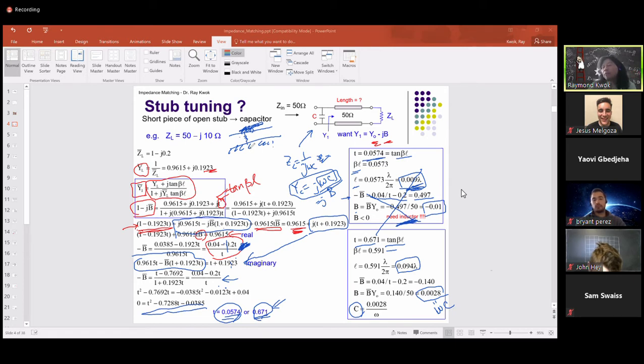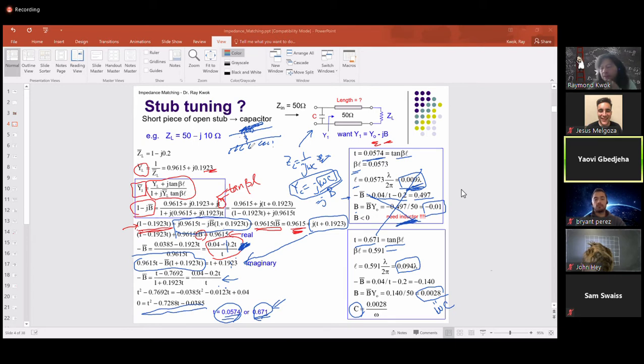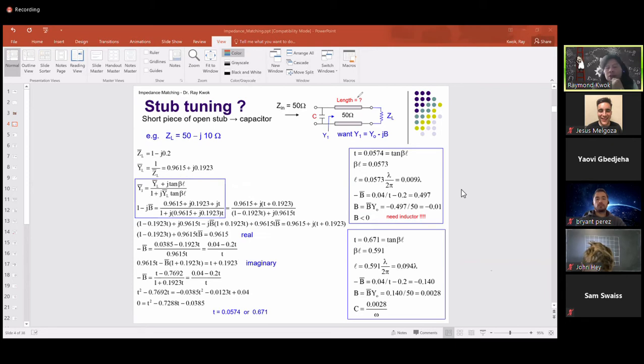That's an expensive process. That's more like a via hole. I cannot keep drilling the circuit board and making via holes to see if it works or not, because that screws up my circuit if it doesn't work. So physically, I'm just trying to describe the whole process. Now you understand what the technicians are doing in the lab. By poking at certain places, how come the whole thing all of a sudden would work? All of a sudden the signal would go through, the return loss is good and the loss is low, right?